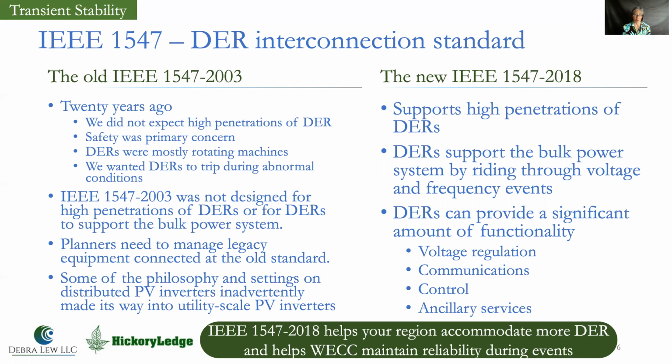So this old standard wasn't designed for DERs to support the bulk power system. It wasn't designed for high penetrations of DERs. The new standard that just came out a couple of years ago supports high penetrations of DERs, and it requires DERs to support the bulk power system by riding through the voltage and frequency speed bumps on the grid.